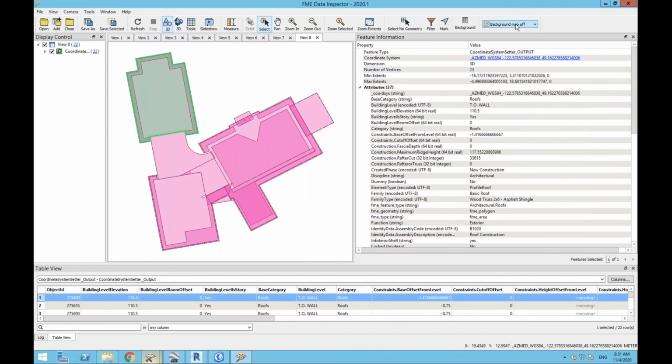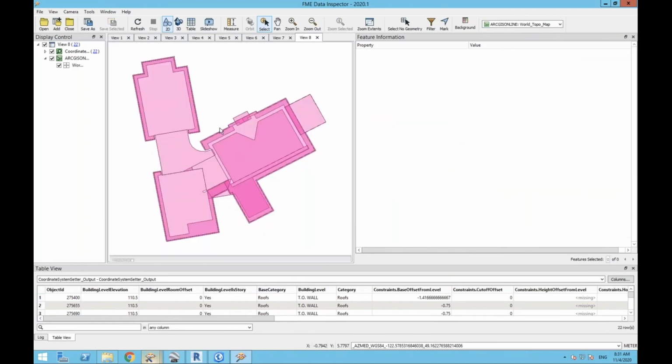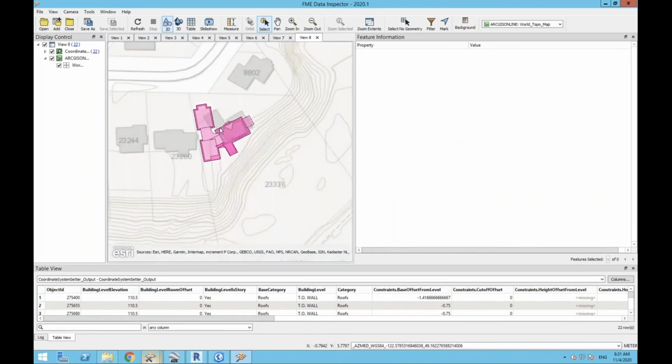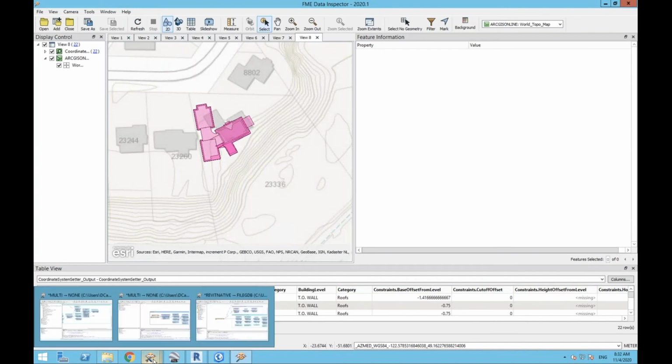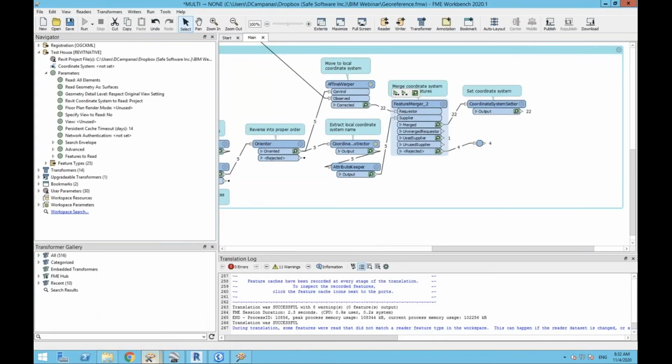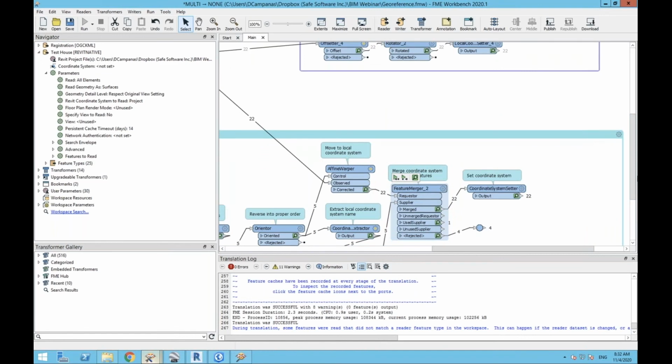And if we look at this, now that it's in its corrected state, we bring up our topo map again, zoom out to where we can see things, and lo and behold, it is in the right spot again. So that was just the basics of ways to georeference. And again, the preference is that if you have survey information, use it. These sort of do-it-yourself methods are kind of good if you're in a GIS type environment and you don't have to be narrowed down to the nearest centimeter or anything. These should be pretty good to the nearest meter.